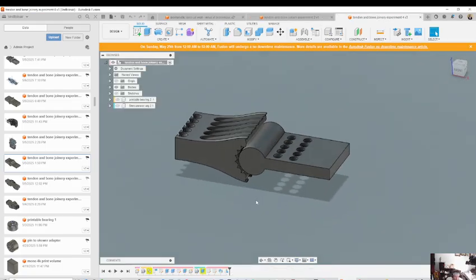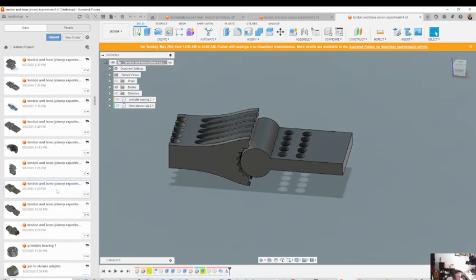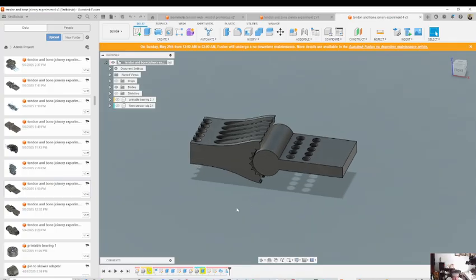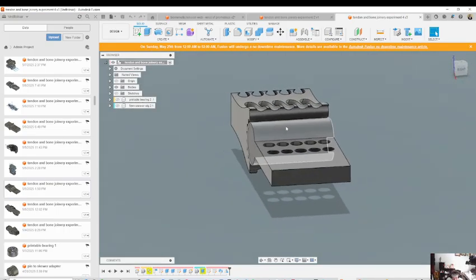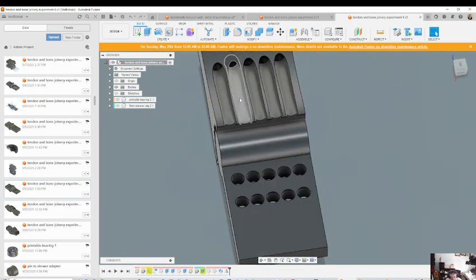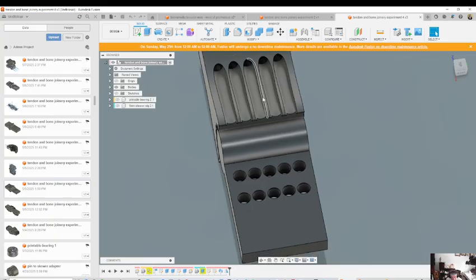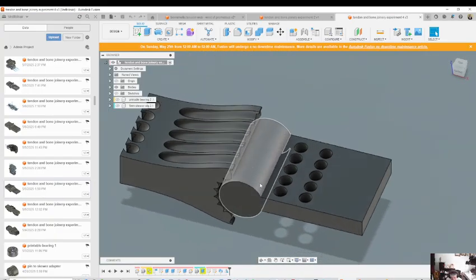Now then I started to move into a different level of understanding of the same components. This one here, I decided to let go of many of the cleats. I decided to replace the cleats with a series of holes that are well situated, because the holes that are well situated would act as a cleat during assembly. So as I pass a string through those, it creates this mechanical connection where the parts are forced to interact.